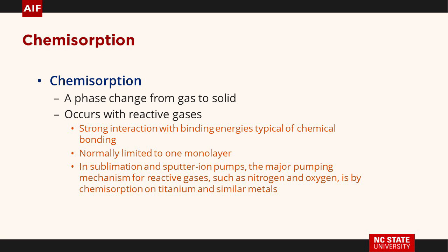Chemisorption, change from a gas to a solid. Some of the pumps you're going to see, we'll show them a little bit later, like the ion pump, use titanium as a surface, a fresh titanium surface. It's very reactive. So the gas molecule hits it and is trapped by this chemical surface.